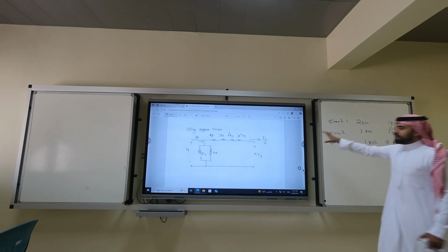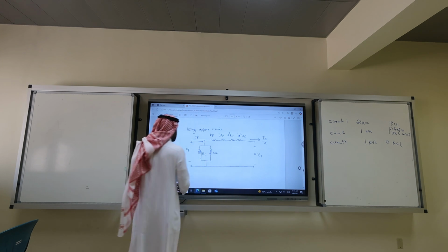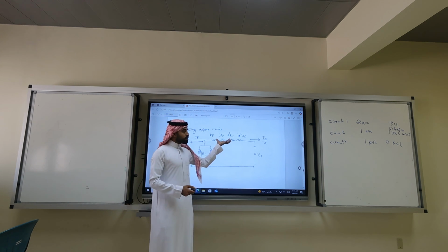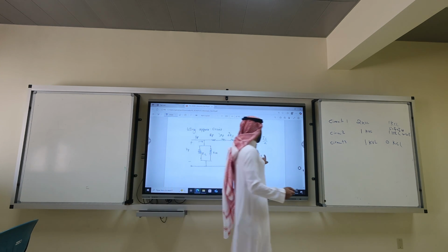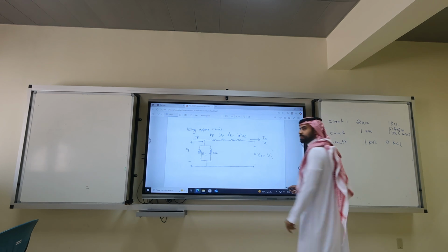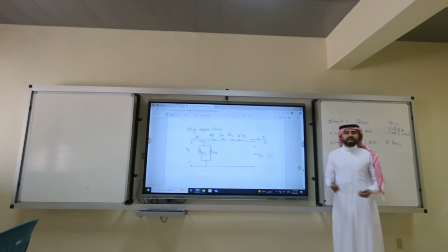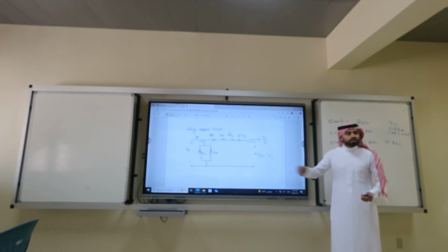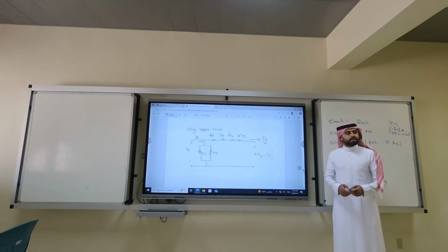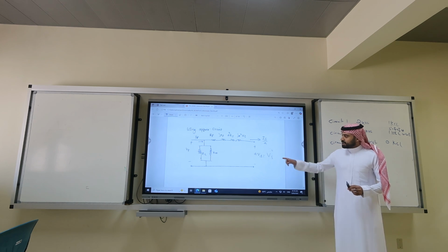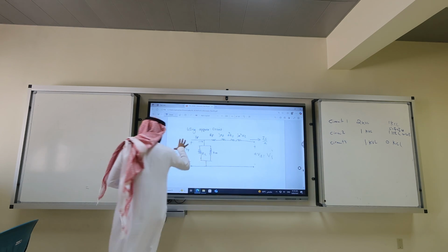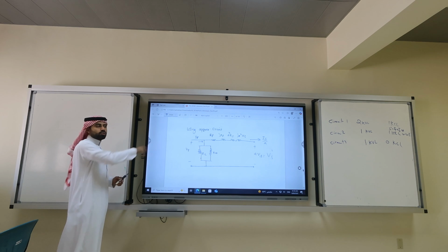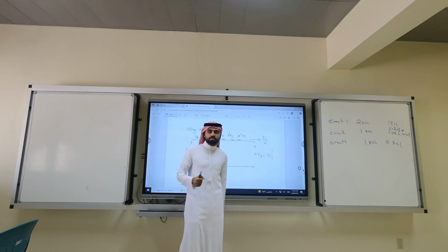So in this example, he used the KVL, which is plus VP minus I times those impedances minus VS. Is this AVS or VS prime? That is AVS prime, same. Is this referred to the primary or the secondary? Secondary. Wrong. Primary. Get it now? Yes. If you see VS prime, then it's referred to the primary. If you see just the VP, then you're referring to the primary. If you see just a VS, then you're referring to the secondary.